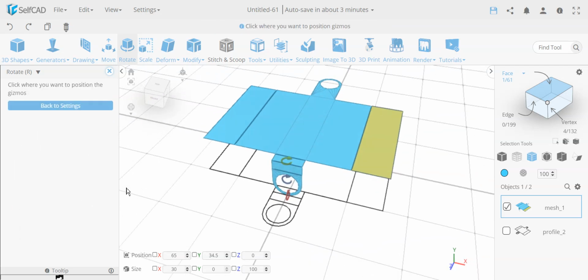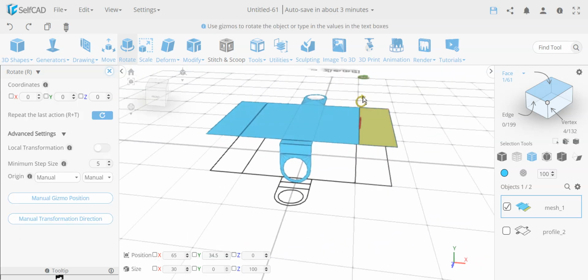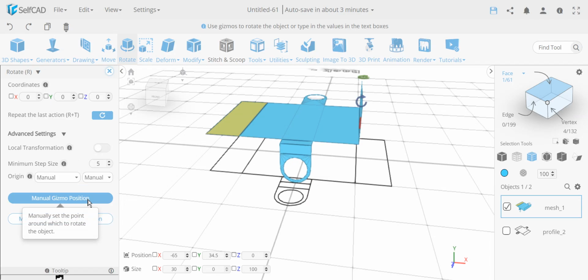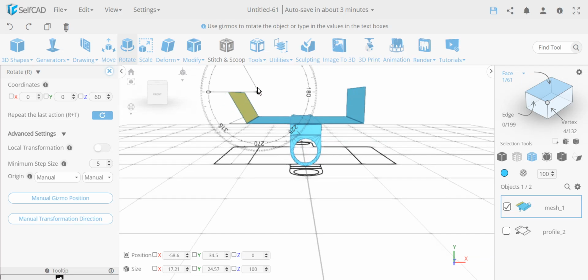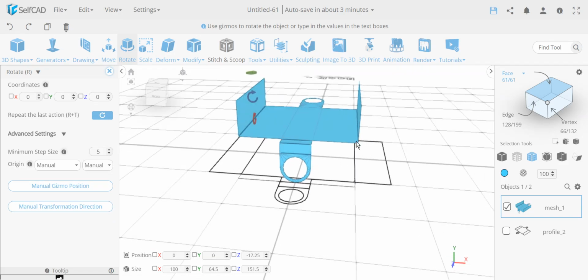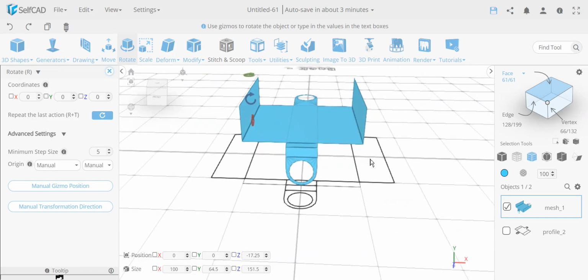I need to change the gizmo position, snap over here, and here we're going to move it up by 270, and then over here this should be a manual position should be a 90 degree, I think. So let's see. Now we're going to move this up by 90 degree in the Z. Now there actually, you may think this is actually all 90 degree angles. That's true, but if you think about from the perspective of the angle from this gizmo, the rotation, if something is already rotated 180 degree based on the rotation plane, we need to add to 180 another 90, which is why we get 270. So yeah, this is a little bit complex the way this rotation works, but I guess the visuals is good.